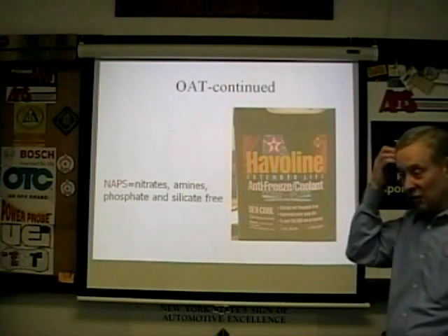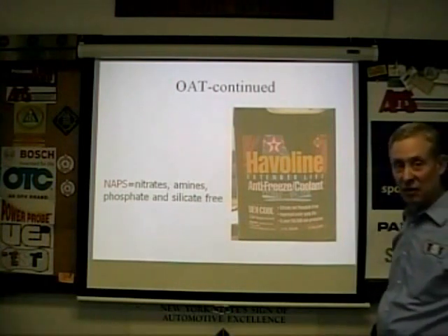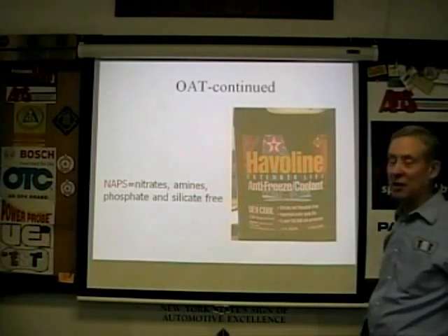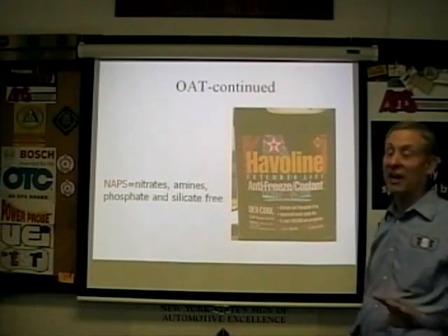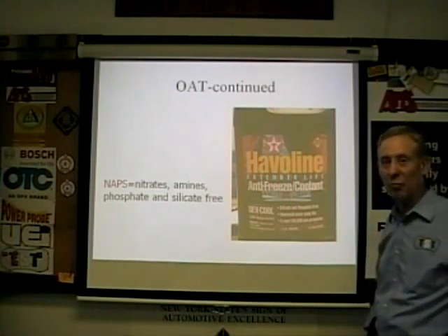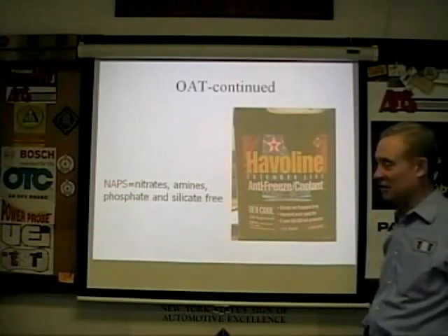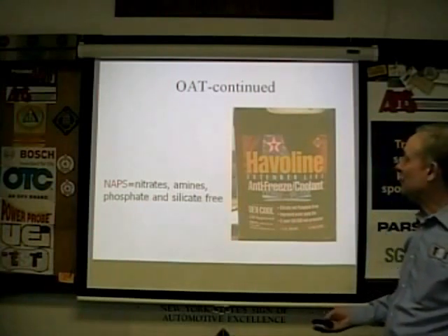I saw an engine once that looked like it had wormholes through the head. Massive coolant incompatibility, and some other shop had put that head on a year and a half earlier. It was a brand new cylinder head on a BMW with holes in it. Very nasty.